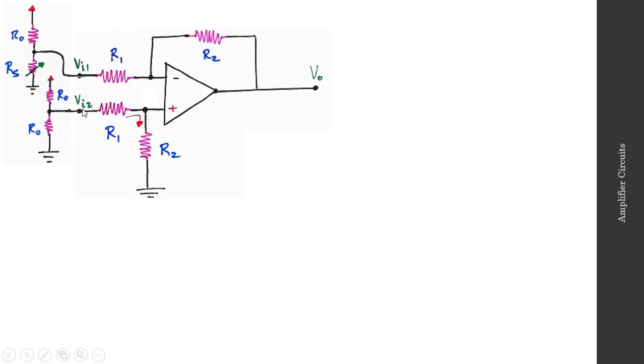There'll be two resistors, I'll call them both R0, as well as another voltage divider, R0, and then I have some variable resistance here. Maybe it's a potentiometer, or maybe in terms of a sensor, it's a temperature sensor. But because I have this potentially small input impedance, I can have some potentially significant loading on this circuit, depending on the value of R0.